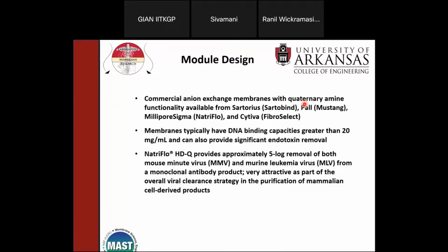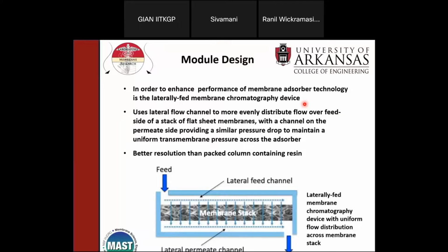Let me see what else I do. We'll finish this lecture, and then we'll talk about emerging membrane technology. Let me talk a little bit about these questions. So you talked about dialysis anyway, right? There's a hemodialyzer problem here, which for anyone who's a chemical engineer should be easy enough to solve, because it's looking at resistance in series just like a plate heat exchanger. If you just replace the heat transfer coefficient with the mass transfer coefficient, you should be able to do it. So maybe you can try that one. For those of you who are not chemical engineers, that's fine. We can discuss it, okay?